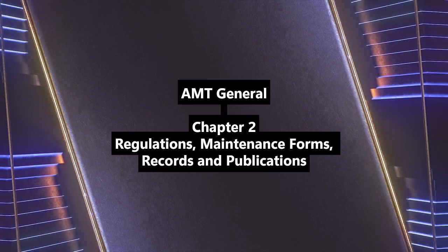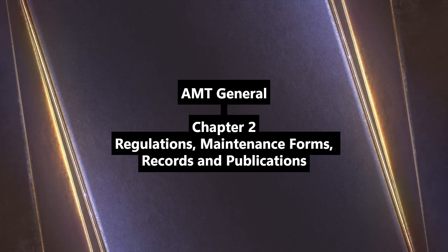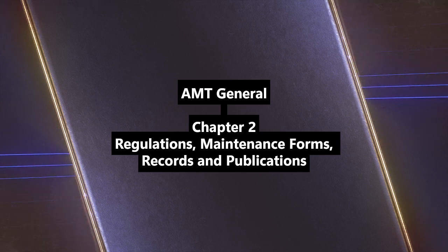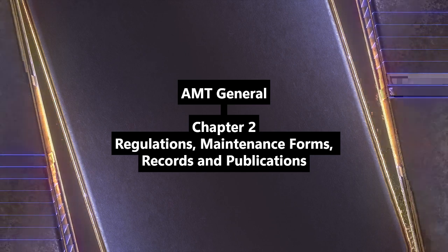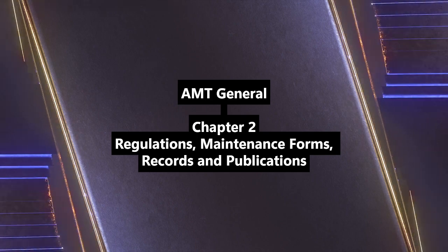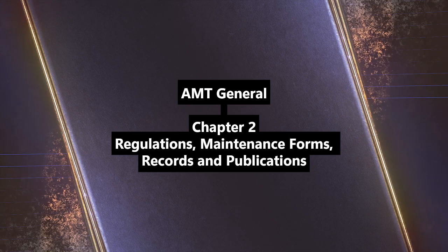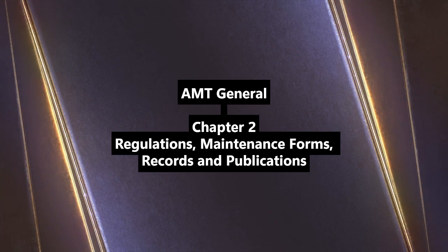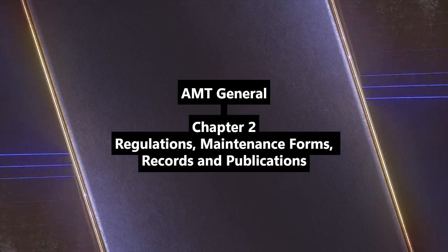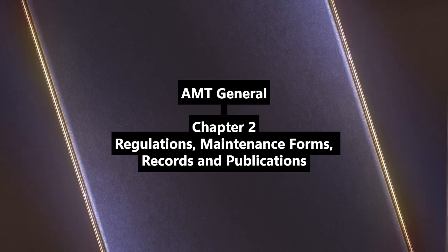Okay. Now, you mentioned something important earlier about which rules apply. Ah, yes. Crucial point. An aircraft only has to meet the regulations that were in effect when it was built. So an old plane doesn't need to meet today's newest design standards. Correct. However, and this is a big however, that does not apply to airworthiness directives, or ADs. ADs are always mandatory, regardless of age. Always. If an AD applies to your aircraft type, you have to comply.